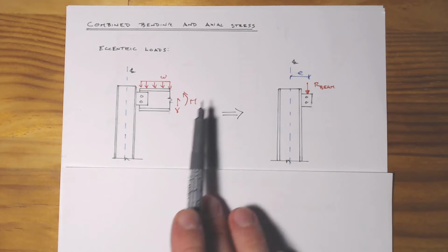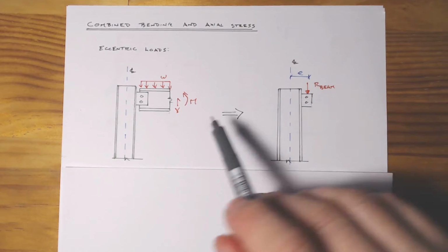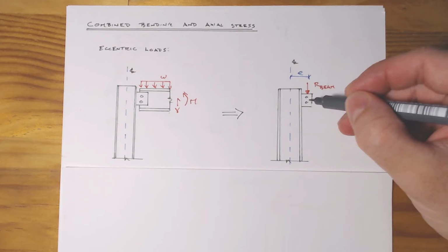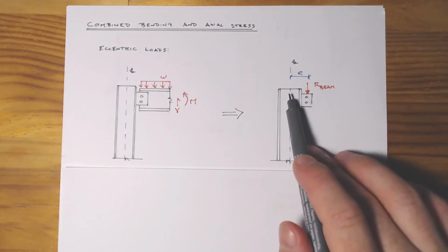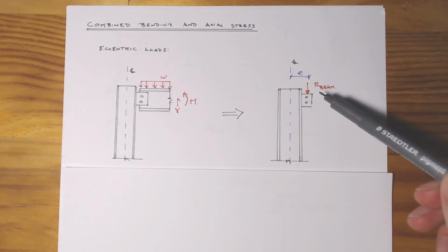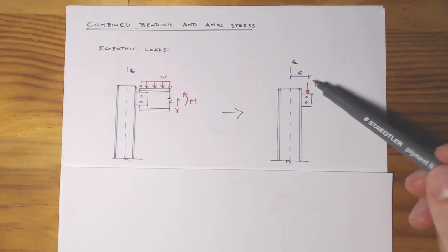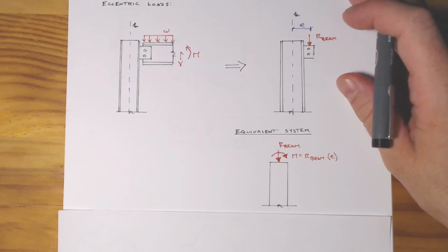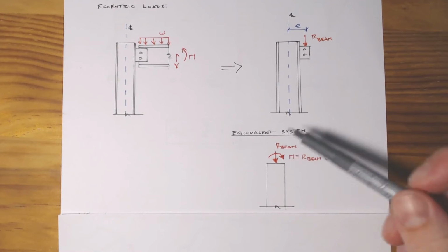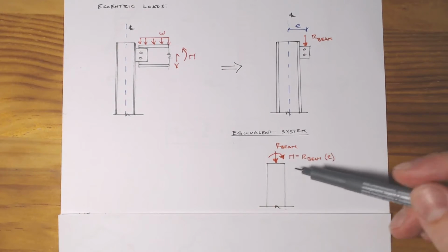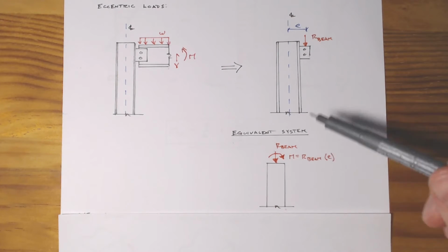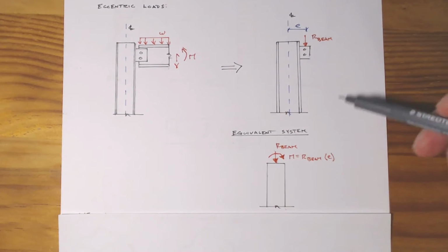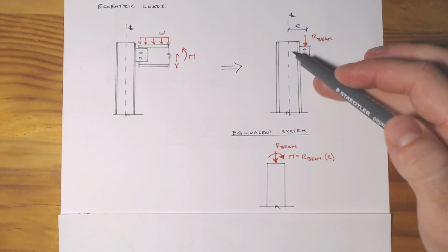And so if we draw our effective free body diagram, really what this shear becomes is, we have a force pushing down on the shear plate with some distance e from the center line. And so if we want to take a force at some distance and turn it into an equivalent system, what we end up with is this force coming in from effectively the shear force on the beam, plus a moment which is going to be equal to the shear force on that beam, so the reaction here at the shear plate, and the eccentricity from that shear plate to the centroid.